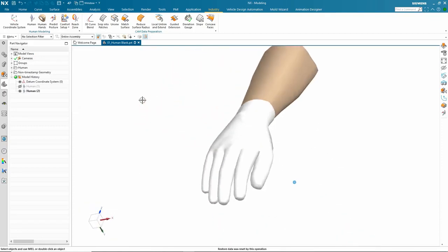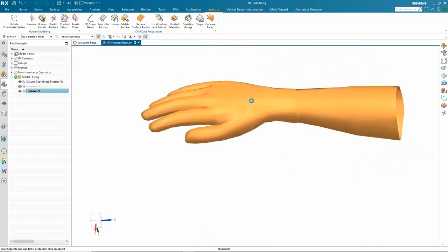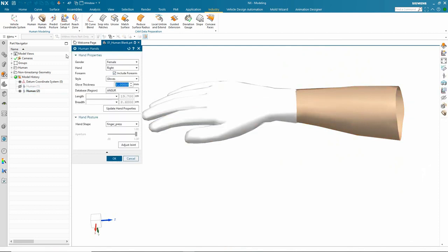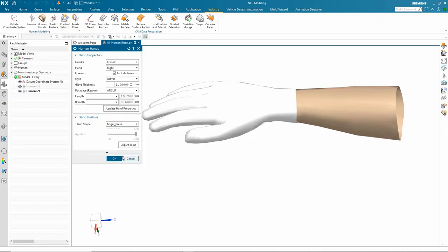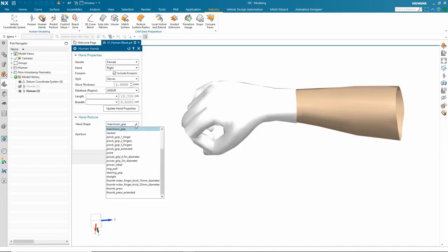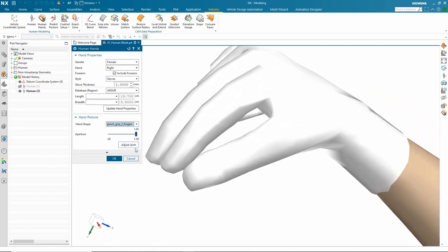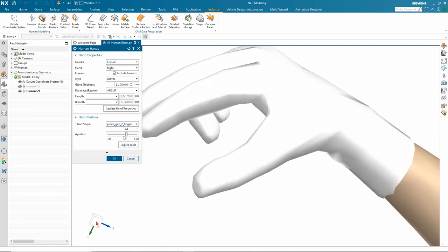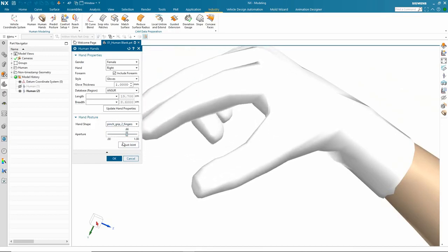And there's my human model. We double click on it, it's going to allow us to edit. So we could change the database, we could take the gloves off, we could actually change position. So much like you've just seen in the previous example, look. So if I was to here say, well, we need something with some sort of grip, or let's go for some kind of a pinch. I can then also go in and change how much that's affected. Look, I could independently adjust every single joint as well.